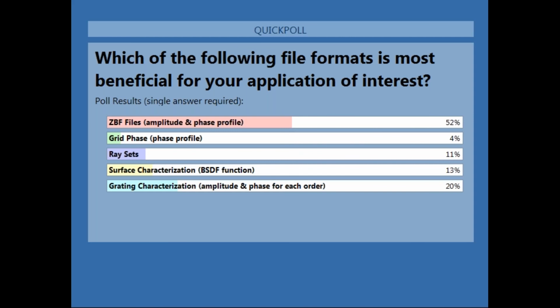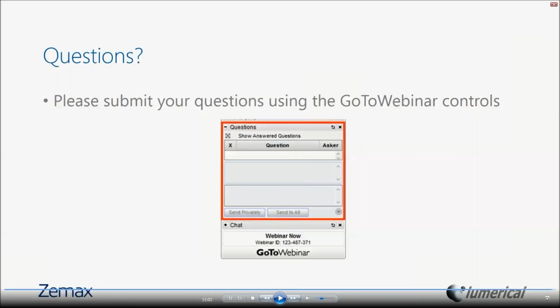And so this tends to be a process where you have to go back and forth and check the sampling, and then check your beam files, and keep changing them for each surface if you're having issues with them. We also have several knowledge base articles discussing how to sample correctly. So feel free to look at the knowledge base if you're more interested in how to sample in physical optics propagation.